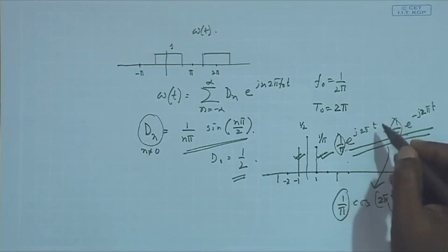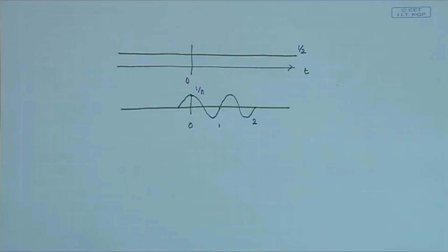So, we do not see the effect of phase, but otherwise the phase effect should be there, and the corresponding cosinusoidal that will be happening will give you exactly the amplitude as well as the phase information. So, cos will be either lagged or leading by that amount of phase. So, this is what you have to do whenever you are trying to draw the corresponding basis signals. You have to take the amplitude from the amplitude spectrum, and you have to take the phase from the phase spectrum. Okay. So, these two pieces of information you have to take and you have to draw the basis signal.